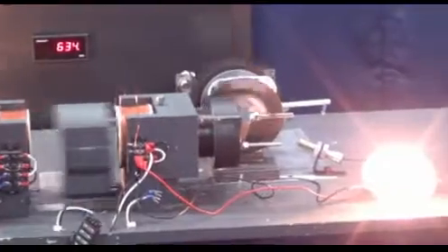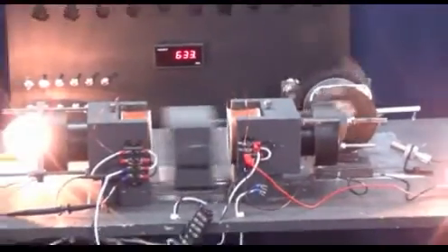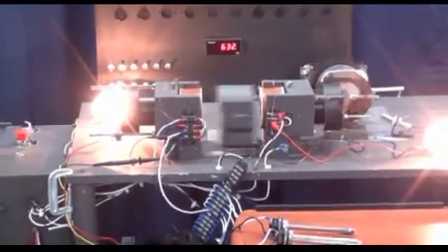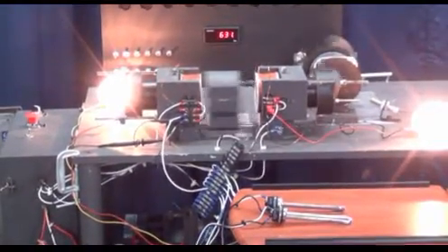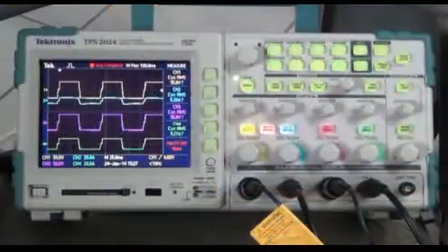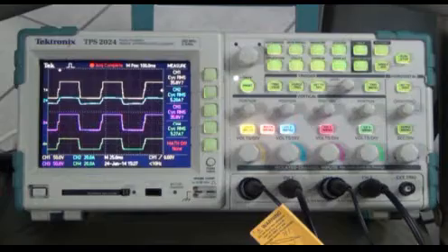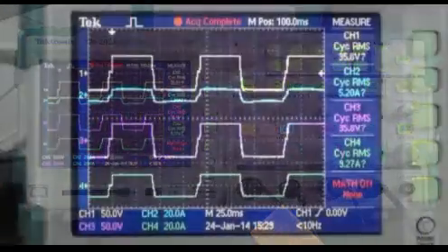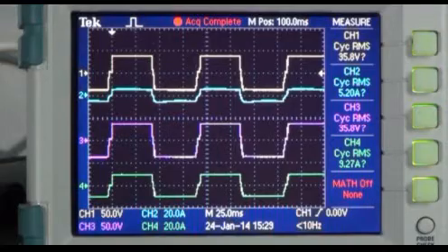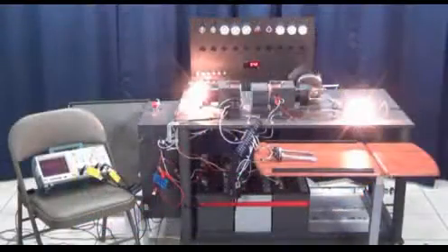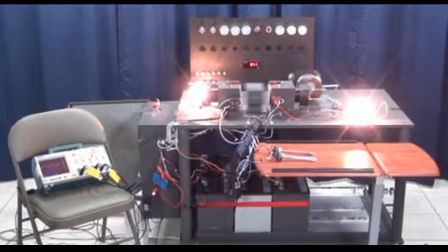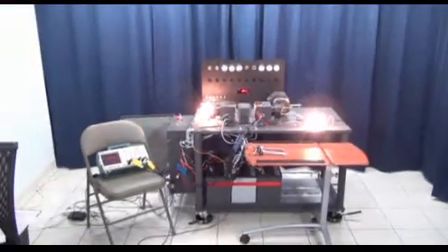It has taken me a long time to figure this out, but it takes me back to what I thought was happening at the very beginning. One thing I've discovered about oscilloscopes is that when they're set to check DC, they include any and all AC in the circuit. But when they're set to AC mode, they reject all DC and check AC only.